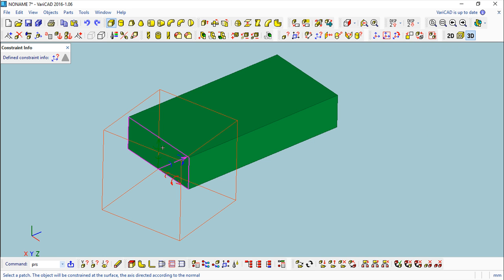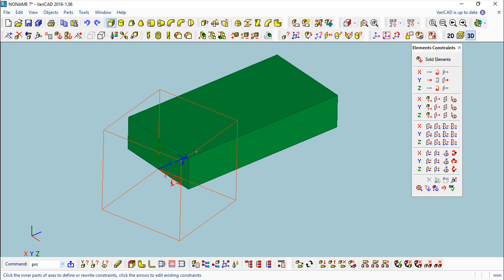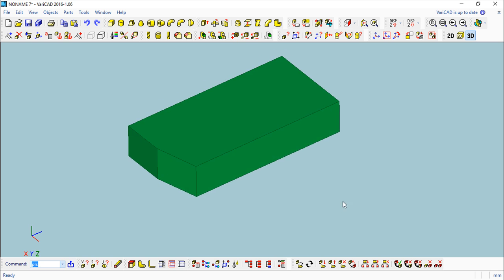So saying this and choosing the surface, you see now we have a constraint in the x on the rotation. On the y we have this linear movement constraint, and we fix it on the direction of y, and again a rotation in z. You have this new symbol with this little mark here and here that says constraint. So do the OK, it is done.